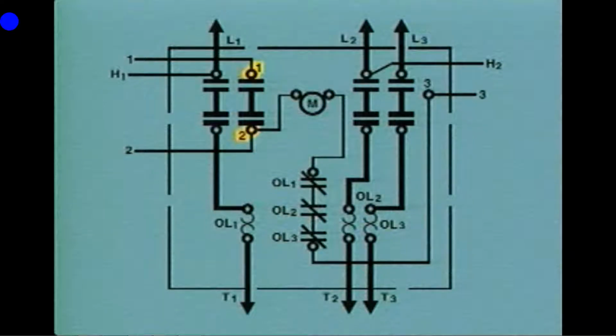and they can be used as a reference during troubleshooting. As on the schematic, the M coil is represented on the wiring diagram by a circle with the letter M inside of it. One side of the M coil is connected to maintaining contacts and the start button at connection point 2.